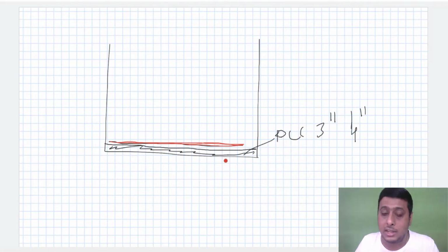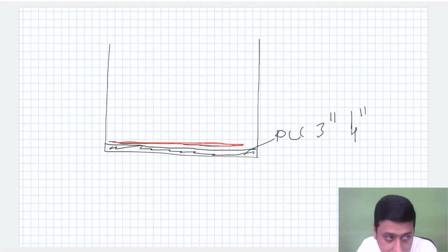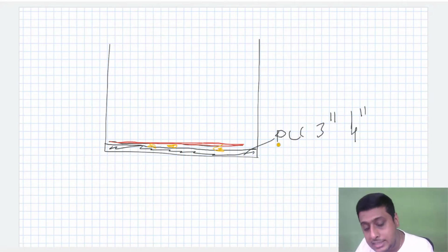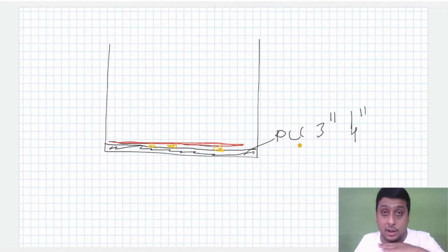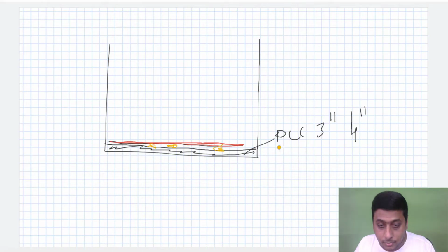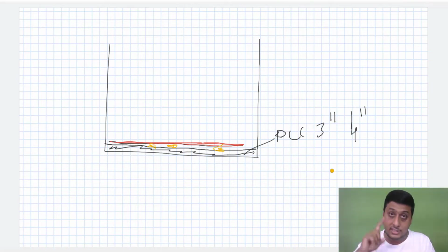Below the mat, we have put the covering blocks. Here, what you can do is lay the covering blocks at regular intervals and put the mat on them. When we do this PCC at the proper layer, put the covering blocks, and then put the footing mat, the mat will not go and sit onto the soil because the covering is there. That is the first reason.